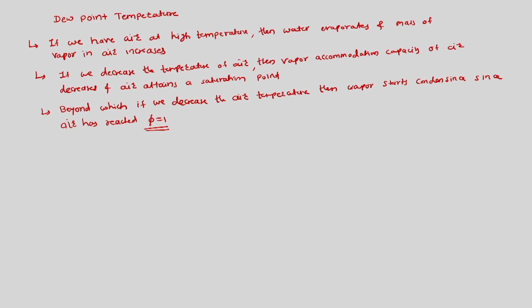the air. We actually are seeing in point 1 that if we heat the air, then basically temperature of the mixture increases, and since temperature of the mixture increases, we have more possibility of having vapor in the air, since air's vapor bearing capability would increase.